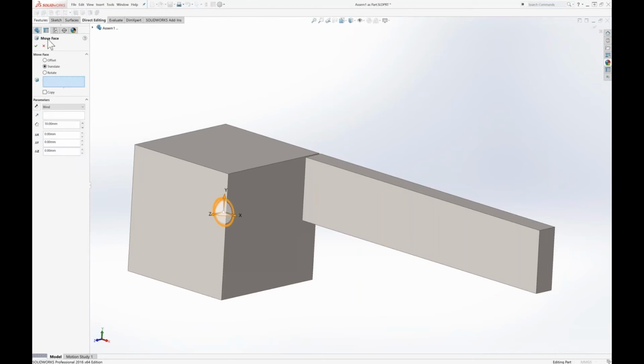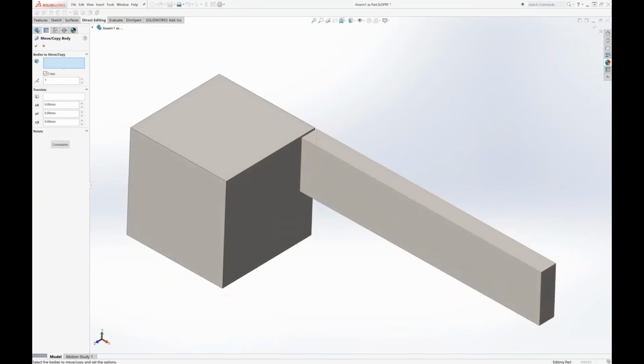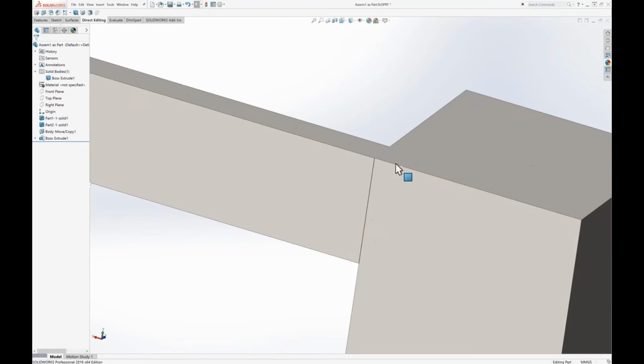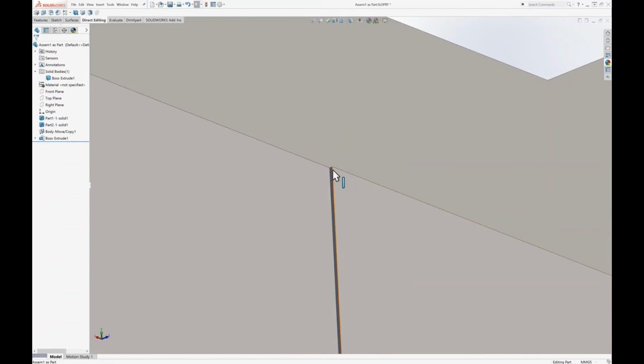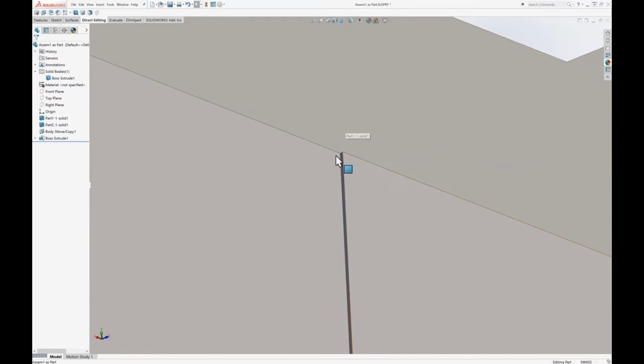the way it is in real life is that this wouldn't be neat and square like this. What I would have more typically is something that's on an angle, say, like this. And then if I do my extrude operation, or combine, then I'm left with this sliver face and this short edge in here, which is where the merge operation creates all these small problem faces.